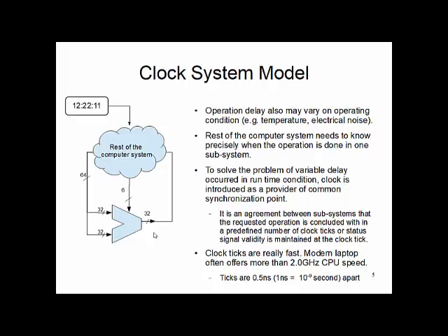If this specific signal changes its value from 0 to 1 and back to 0 and repeats this under a fixed time period, then we establish fixed reference time points. Then we can say, if I send an input at this time point, I expect to get a result back, let's say 10 or 20 ticks after.